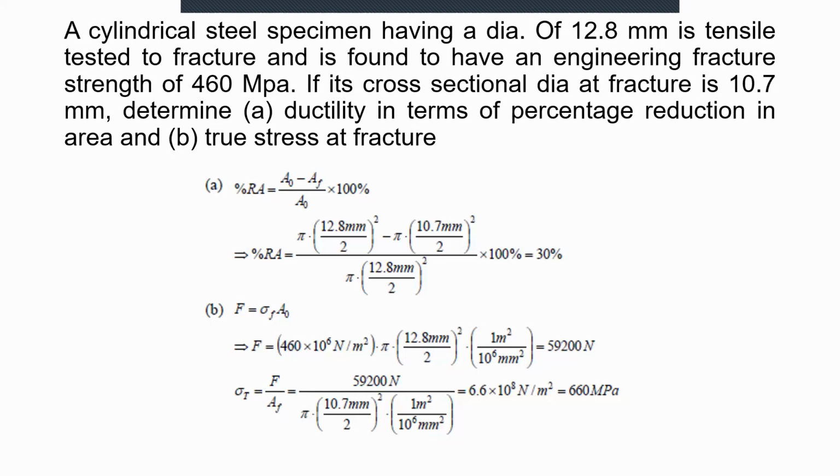Now you have to find the true stress at fracture. I have found it analytically, but there are also relations for true strain and true stress, if you have read that. The true stress can be given in terms of the engineering stress as the engineering stress times (1 plus e), where e is the engineering strain. Similarly, the true strain can be given as the logarithm of 1 plus the engineering strain. So you can use those formulas also. Here I have found it analytically, so that doesn't need you to remember the formulas.